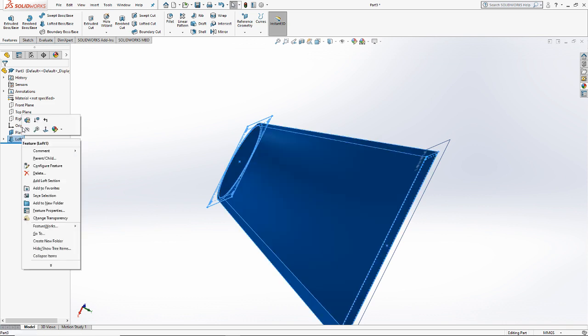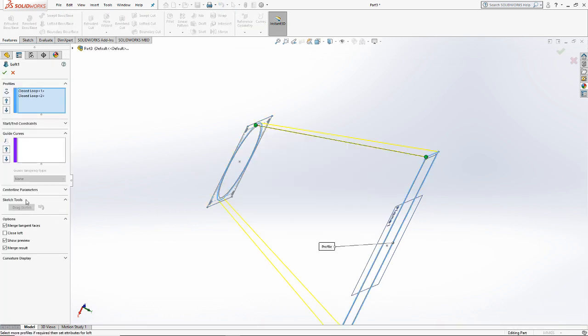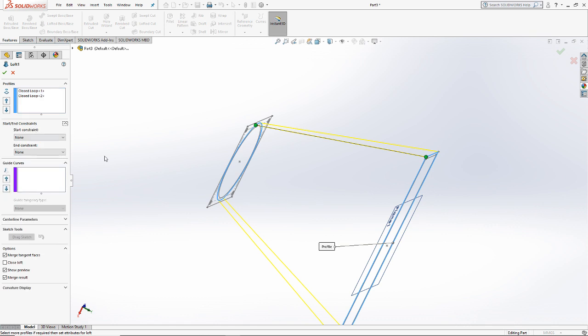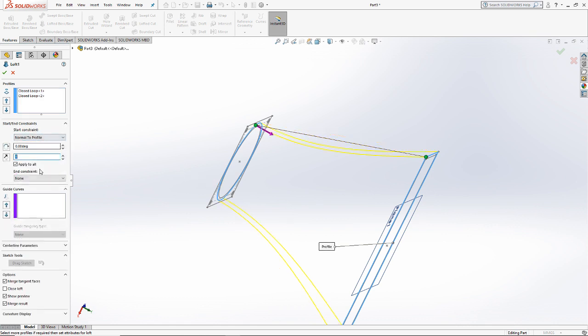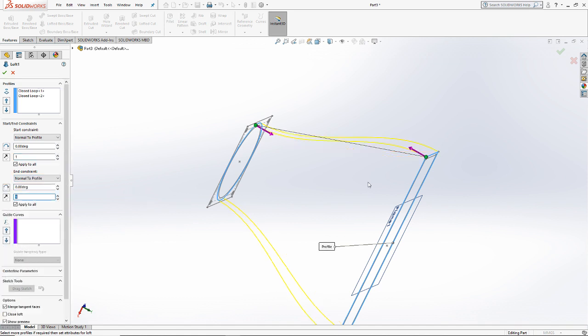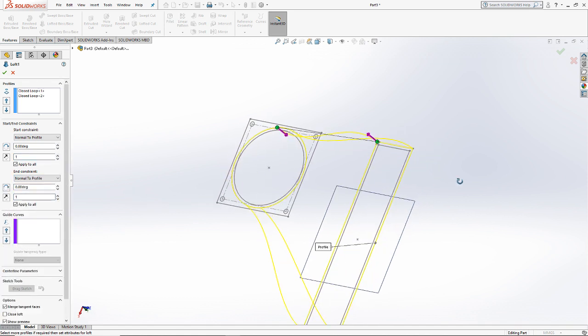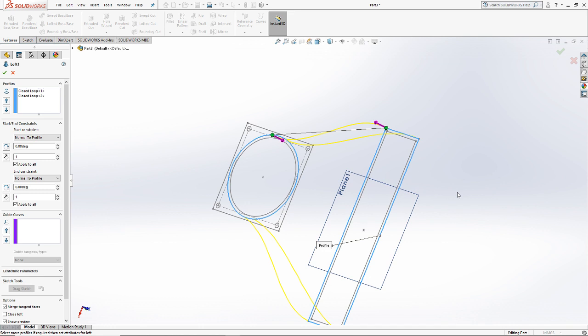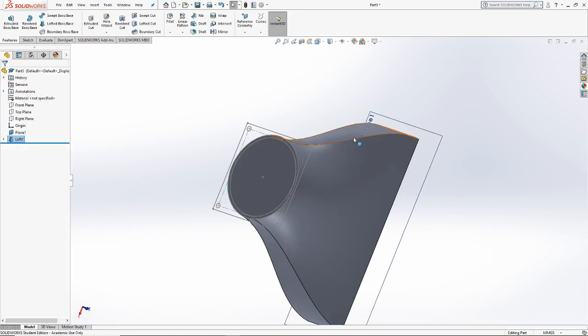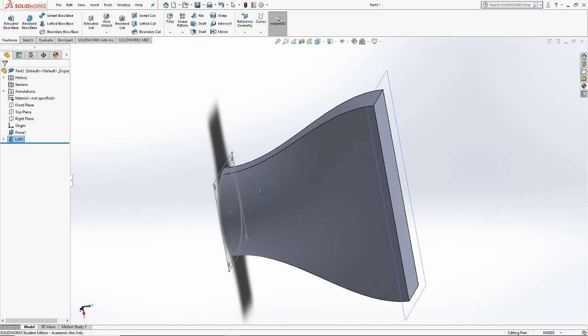If I wanted to continue that, I could, for example, indicate some starting and ending constraints. I could tell it that I wanted it to specifically extrude the initial and end points of that loft so that they came away orthogonally to the sketch that I had drawn. Something like this might look more organic.